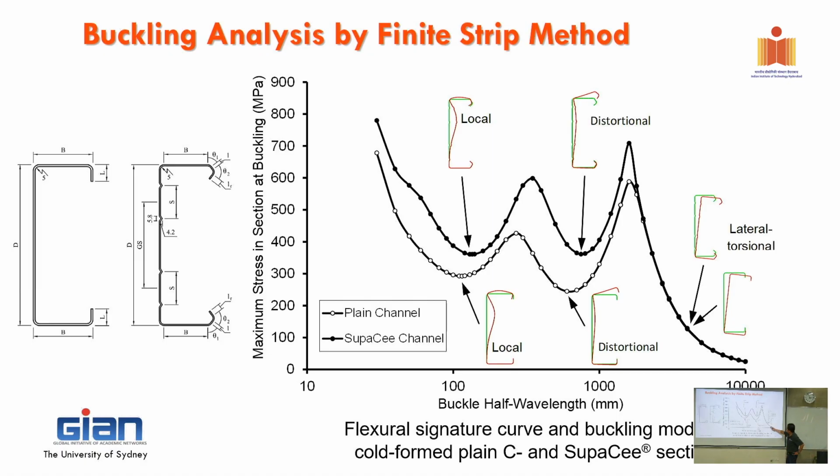Interestingly, you can see those curves are matching. So what does it mean? After distortion, we have lower moment capacity. So it doesn't matter if there is a little change in the stiffener, because it doesn't change Ix or Iy a lot, right? Then there is no problem with the flexure torsional buckling.